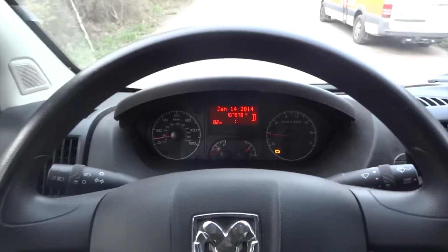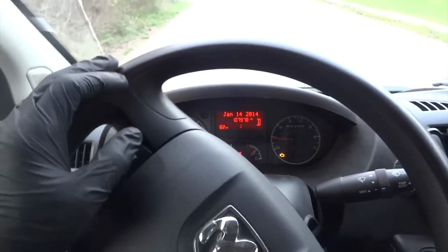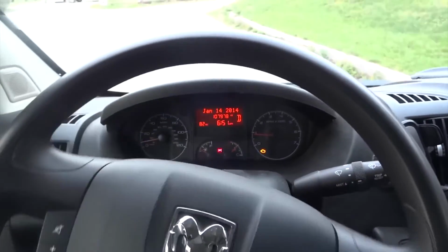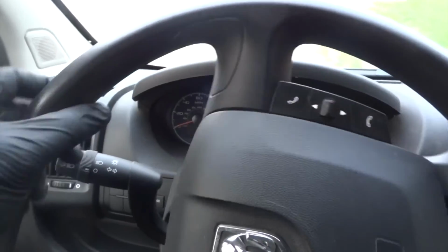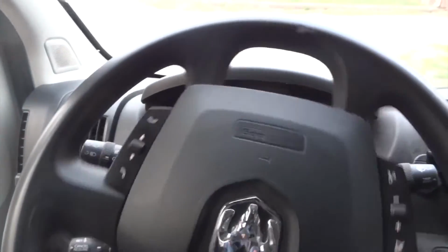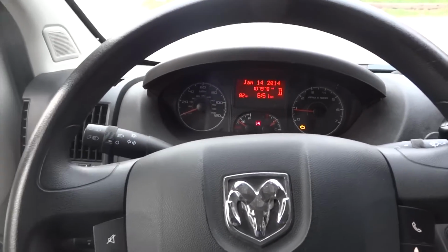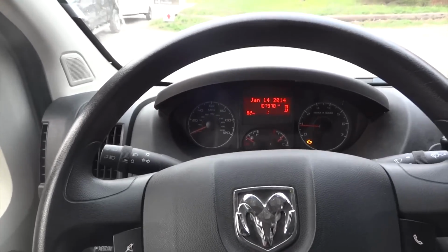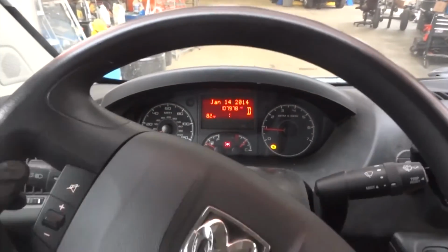Now, one thing I just thought about, I thought I would mention it, is a partially clogged DPF. I want to do a forced DPF regeneration first before we try to open up this EGR, because we can have a DPF that's partially clogged that can cause excessive back pressure in the exhaust system, which can cause the vehicle to lose power. It's something that we can try to see.